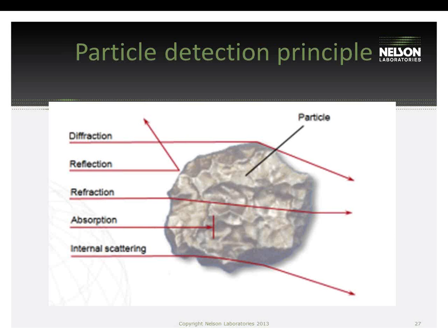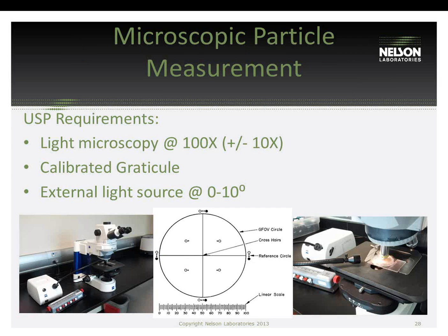An example would be an air bubble. If an air bubble is drawn up into the sensor, that bubble could essentially cause scattering of the light or some type of refraction. The same as colloids. If some type of oil or silicone gets mixed in with water, it can cause the same phenomenon. So that's where the microscopic method comes in, which we'll discuss in a moment.